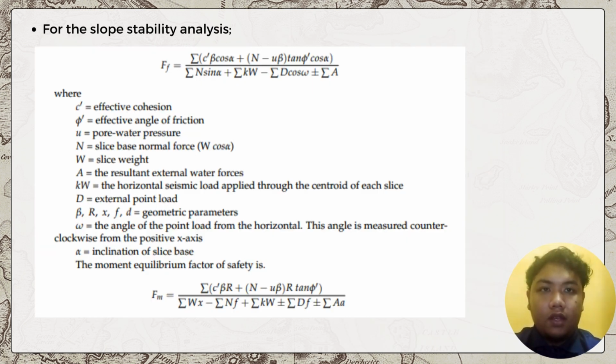The slope stability analysis was performed by adopting the limit equilibrium approach in Slope software, based on the determined shear strength parameters along the most likely failure planes. Slope allows a variety of methods to determine the safety factor, but in this research the Morgenstern-Price method was used due to the simple geometry of the Jika Gali landslide and its popularity among different researchers.